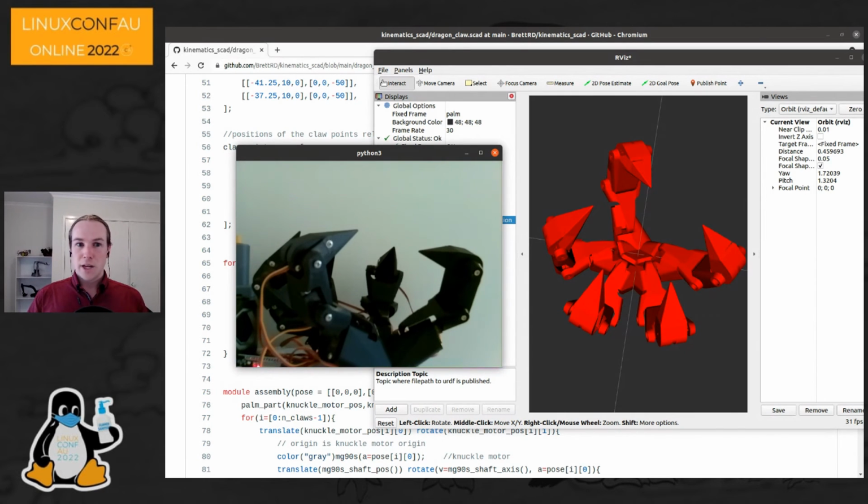Like I mentioned, for map generation versus obstacle avoidance, if you have a 2D LiDAR, you can set up little zones where if you detect a hit within a zone, you know you've got an obstacle that you need to avoid.